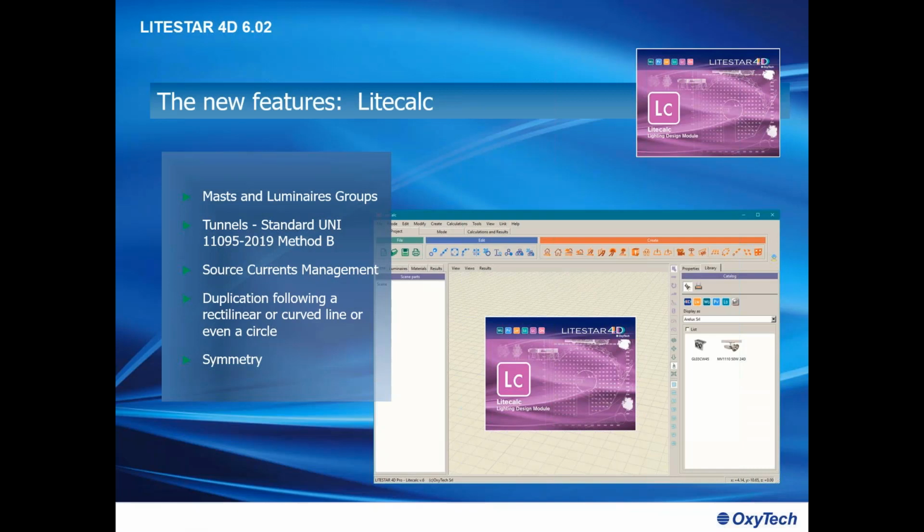So more and more it is necessary to give exactly what you need for the lighting of the road. So for example, over here in Italy, over here in Europe, we have the definition of the class, and through the definition of the class, you have the definition of a value, minimum value in terms of luminance. So for example, M3 is 1 candela per square meter.